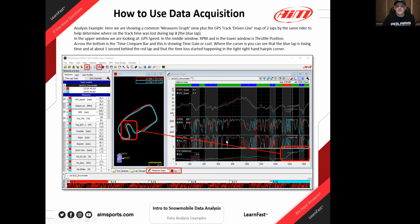But typically what you're seeing, John, is something that happens in your first session before you've had a chance to put in the lap marker or the track map, load the track map into the data logger, so then the rest of the weekend you won't have that problem. And if it's a track that maybe you even have a chance before the race starts, go out to the start finish line with your phone. There's lots of GPS apps where you can get the latitude, longitude of the start finish line just by walking up to it and getting that, and then going in and making the track map ahead of time, the start finish line, and sending that into your data logger.